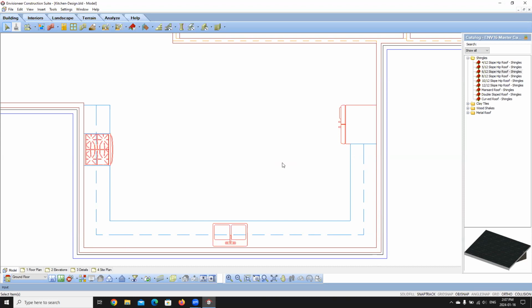When inserting a kitchen island, it is recommended that you leave at least 36 to 42 inches between the island and the bank of cabinets to ensure there is a good working aisle. You can insert temporary guidelines to help you place the island the correct distance away from the cabinets.